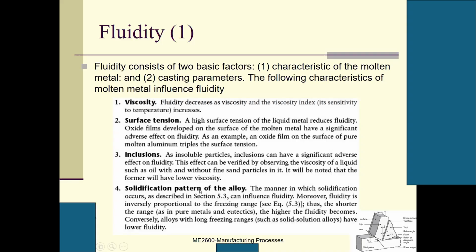Inclusions. Insoluble particles, or inclusions, can have a significant adverse effect on fluidity, and this effect can be verified by observing the viscosity of a liquid such as oil with and without fine sand particles in it. It will be noted that the former has lower fluidity.